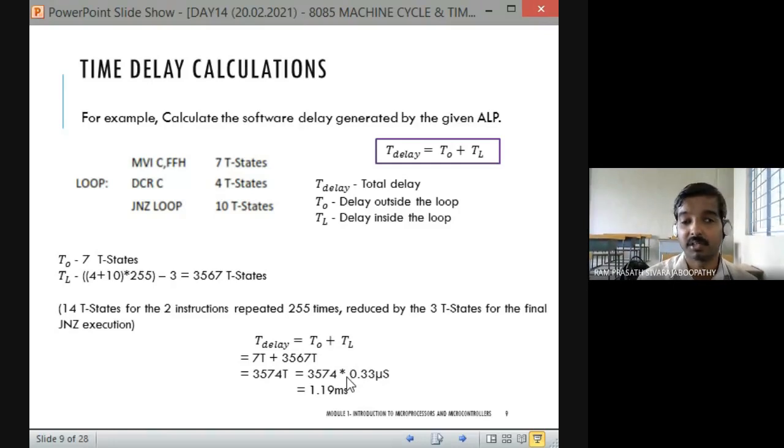Fine. Okay, I have just one question: what happens if I put 00 here? If I put 00h instead of FFH, what will happen? How many times will this loop run? We should know all this; only then can we write a delay program. Any idea? Since we put FF, it ran 255 times. If we put 00 here, how many times will it run? Just imagine and tell. Think and tell.